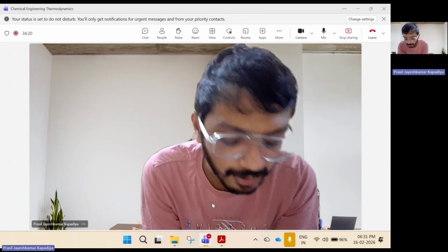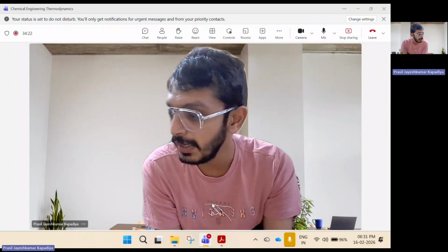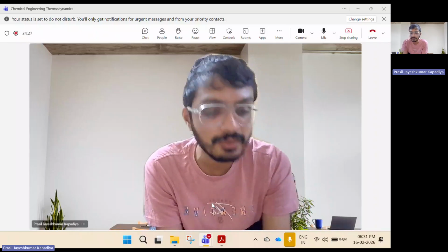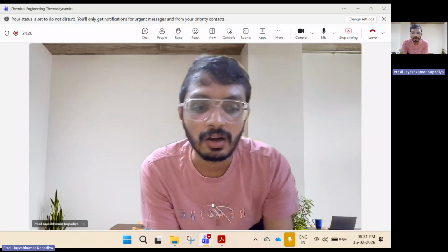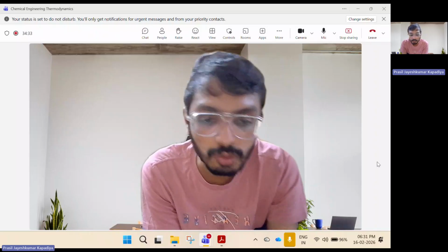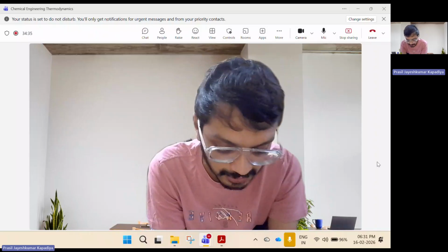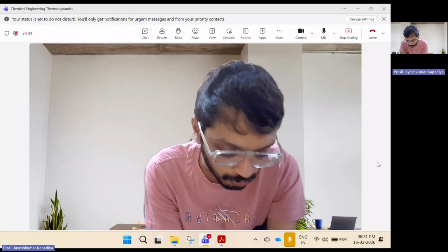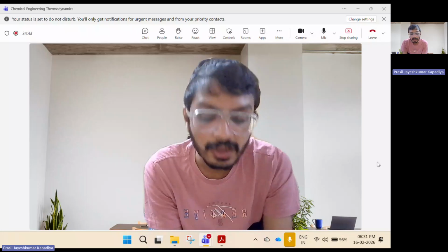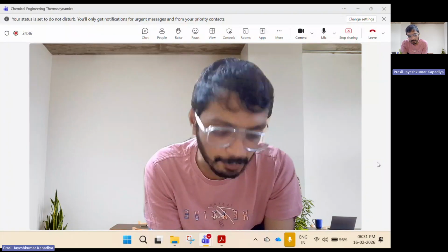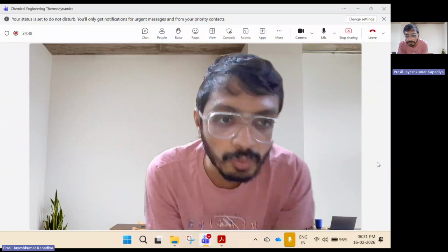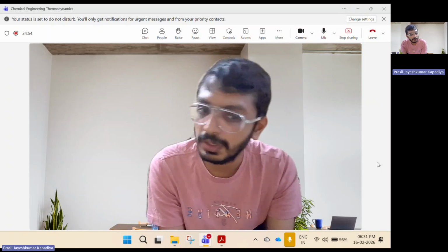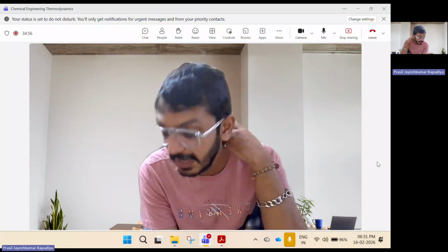So here we learned that we can estimate residual enthalpy and residual entropy using the first equation of state, Peng-Robinson. We had a look at the Van der Waals equation of state, how to perform these calculations, and then from there we moved to Peng-Robinson. We have not derived the value for the Peng-Robinson equation of state. Then we took the second approach, the compressibility factor approach, and we tried to include reduced temperature and reduced pressure in that, and we found the values of TRN, HR and SR.